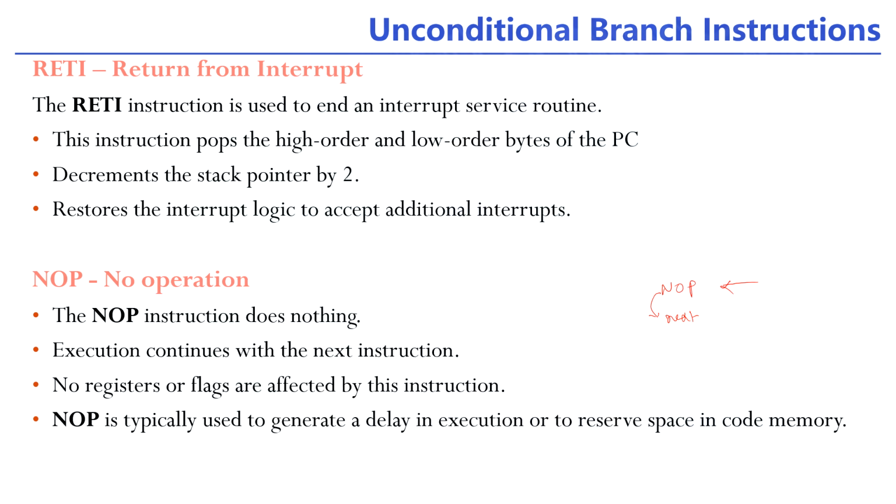So let us see how it will generate the delay in a program. Let us consider that NOP reserves 1 byte in memory and takes 1 clock cycle to complete its execution. It does nothing, but it consumes one memory location, and it consumes one machine cycle for execution.